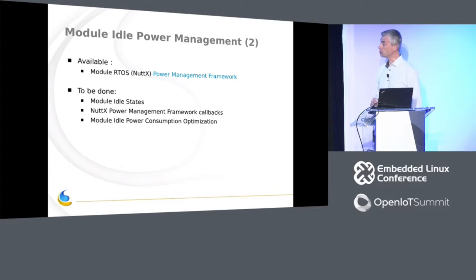So we leverage the NuttX power management framework for doing that. NuttX is able to transition drivers and the system into various low power modes that we have defined. And so that was our job, to find all the low power states we could put a module into, and implement all the callbacks of the new NuttX power management framework, and do the optimization.